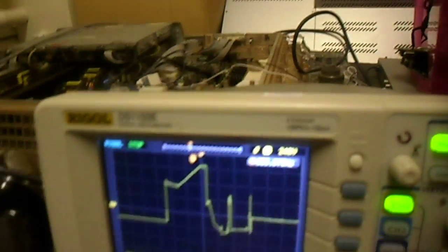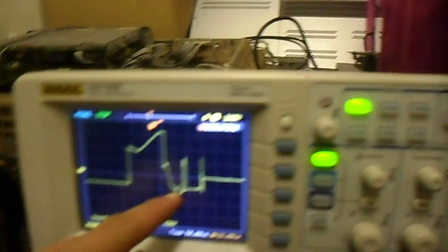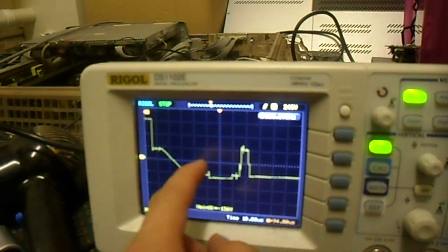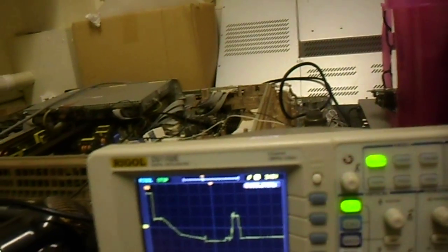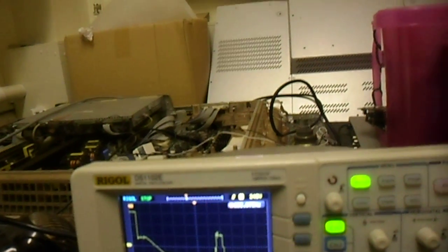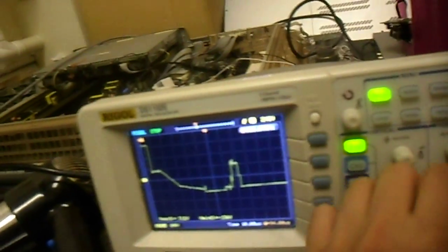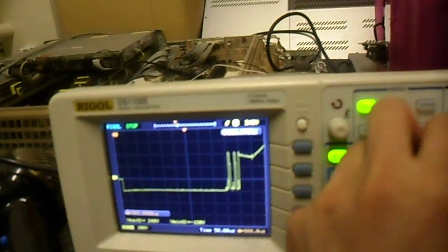And by loading a single bit image onto the panel, you can then sustain it, which is this period here, and the sustain process basically means moving the voltage through from minus 100 to plus 100 on one side, and plus 100 to minus 100 on the other side. The plasma panel experiences a cell voltage change, and this change in cell voltage induces a current, which induces a light emission. So that's a single sustained field, so that's the least significant bit of the panel.